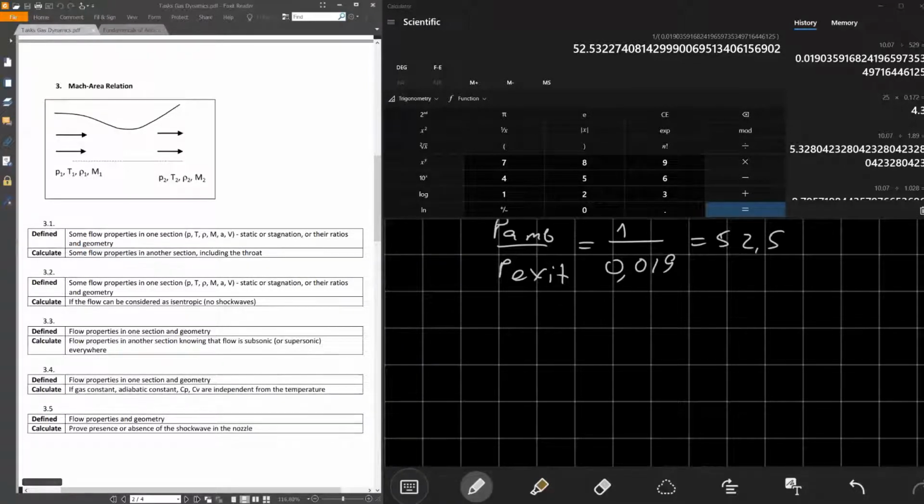The recommendation I usually give to my students is the following: temperature is a definitive criterion to know if the gas constant is changing or can be considered constant. It's really constant. There is a small confusion here when we call it the gas constant, but it's not constant, right? The same for the adiabatic constant and others.